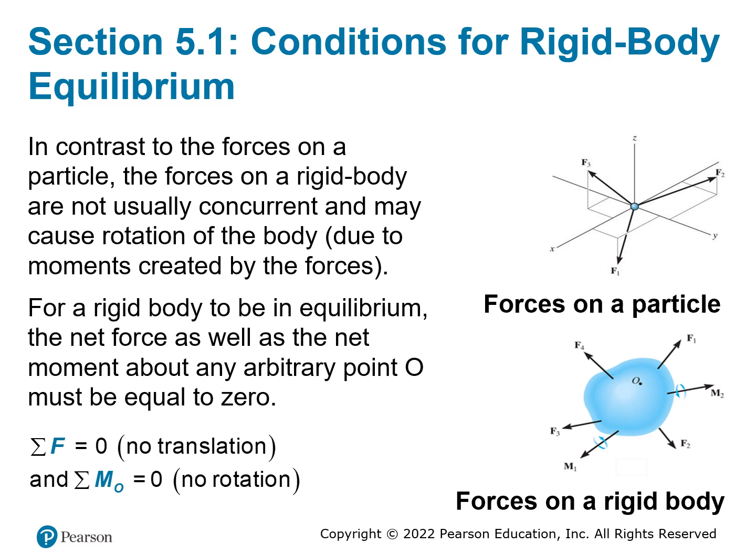All right, so that's first to think about what is the condition for the rigid body equilibrium. And the condition is very easy. It doesn't matter if it's 2-dimensional or 3-dimensional, the condition is always these two. You have a net force equal to 0, and you have a net moment equal to 0.